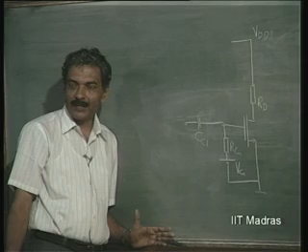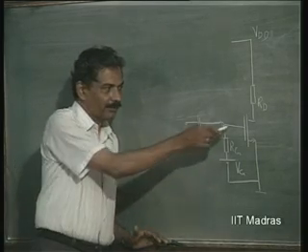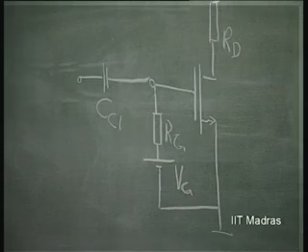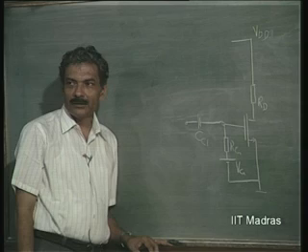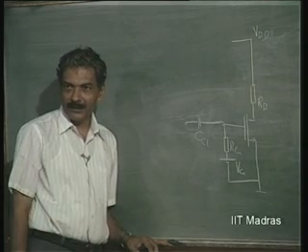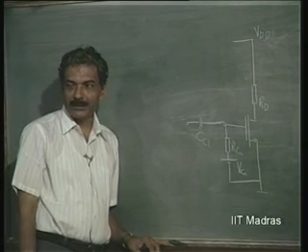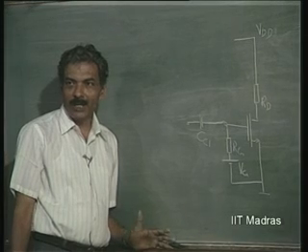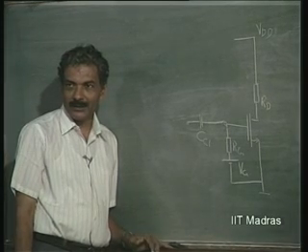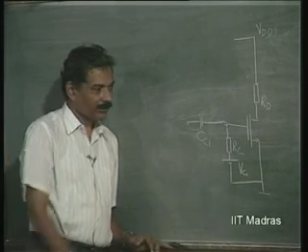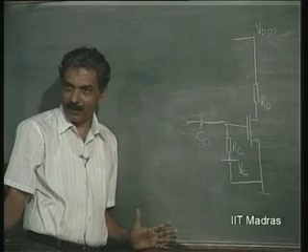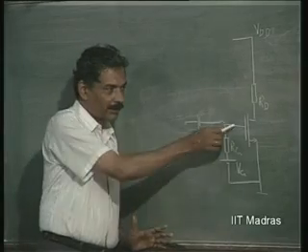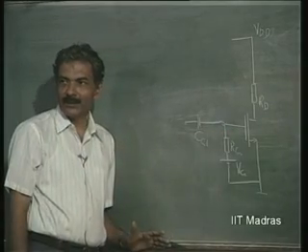let us say, a few hundreds of kilo ohms, because the actual impedance of the field effect transistor is of the order of what? It is an open circuit, right? It is a field oxide. So it is of the order of 10 to the power 12 ohms or so. So you can put even resistances of the order of mega ohms if they are readily available, no problem. This impedance is not going to get affected at all.